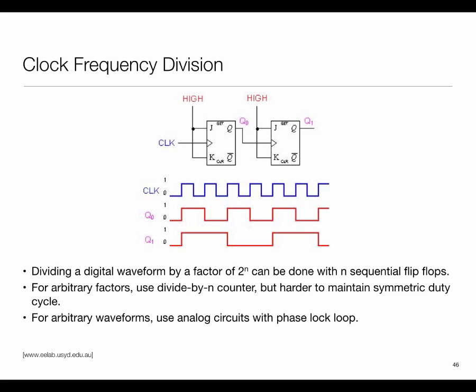Now, one thing to keep in mind is that the frequencies that you use in the system may not be the same as what your clock provides. If you look at any typical processor, it will usually also have some circuitry which takes the clock that you're providing it. That clock could be coming from an external source like a crystal oscillator, or from an on-chip source such as the ring oscillator, but then you feed it into some block which you can program to get the desired frequency.